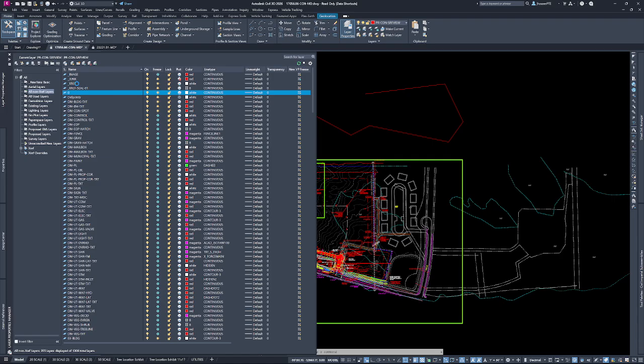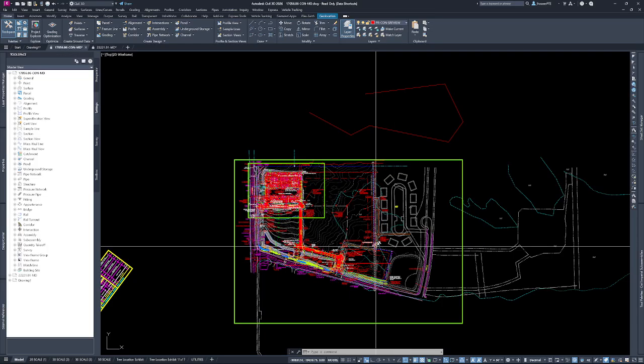And when you're done using those drawings for reference, detach them, get rid of them from your main drawing, and that will help speed up the process and make your drawing much clearer. One of the things that I've been struggling with, even with having separate layers for different projects that we're bringing in, is that the XREFs are just as bold as everything else.